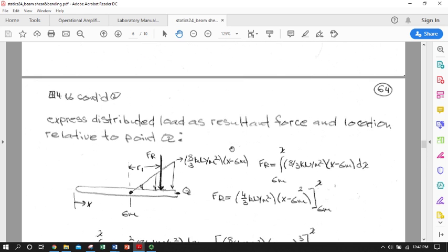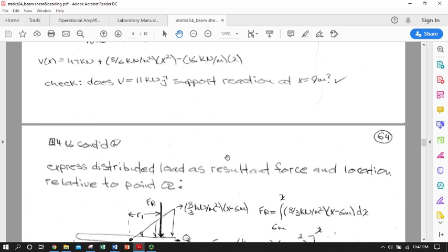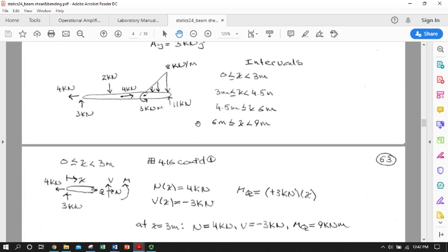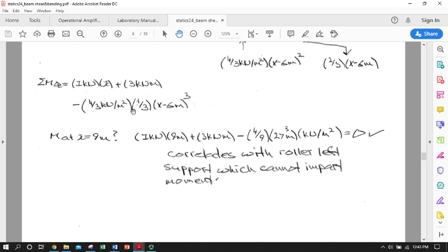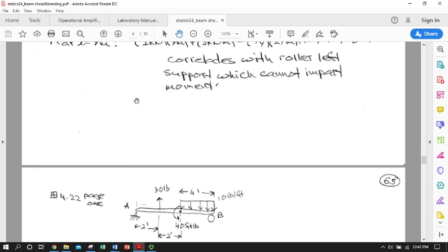So this is actually a very correct but very cumbersome way of stepping through each one of these regions. We did an awful lot of hand addition of contributions to moment from shear, picking up other regions. We didn't do this so much in terms of continuous integration and limits of integration. And well, this is valid, and you can see that it checked. And I'll note that we have the correct order of terms. We got a moment expression that's a cubic term now. If we had a shear that was parabolic, that makes sense.